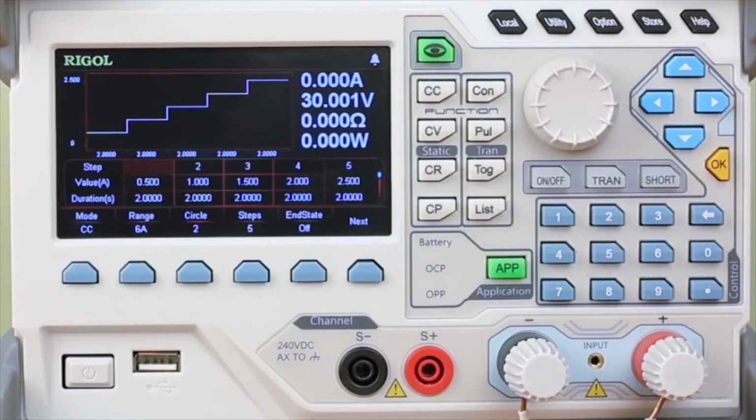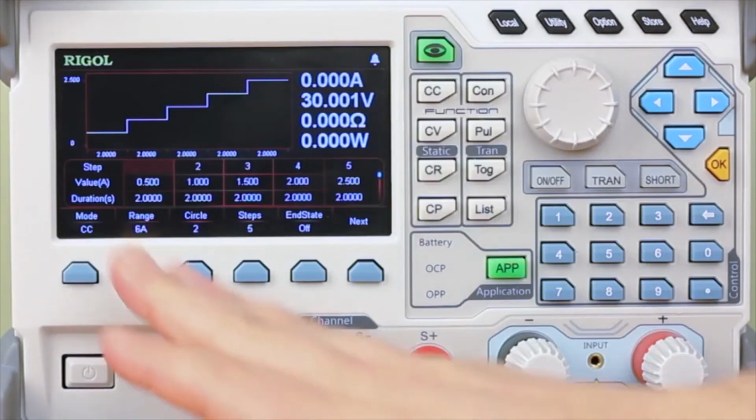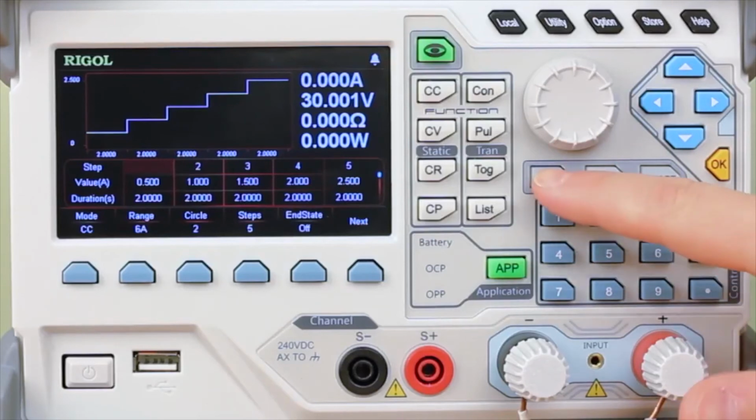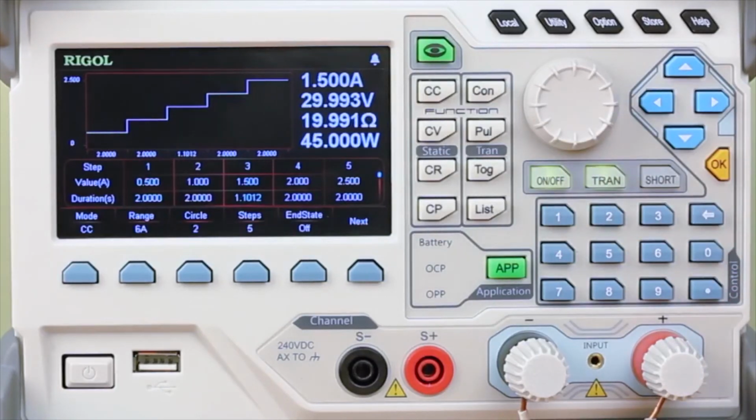The fourth mode in the transient modes is a list. Here we have set a list from 0.5 amp up to 2.5 amps, a stair step of current. With each stair step you can measure current, voltage, power, and resistance. Let's activate that. So here we can see